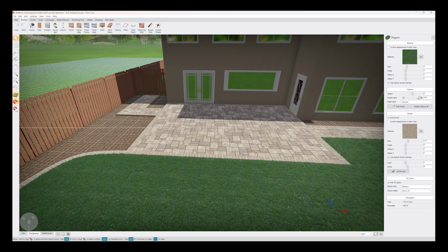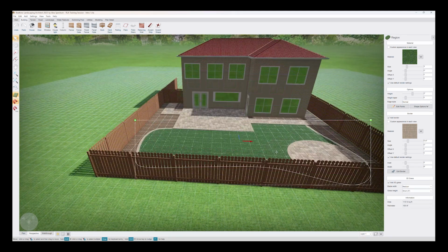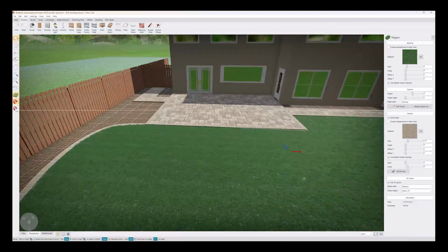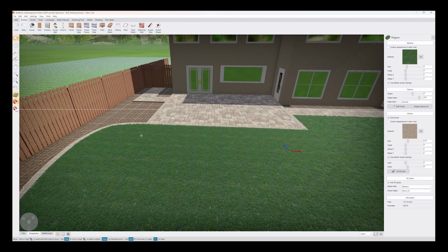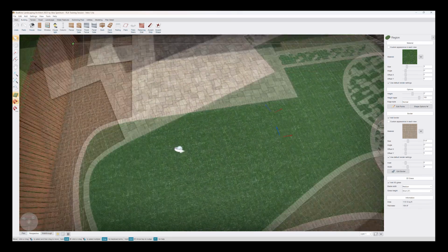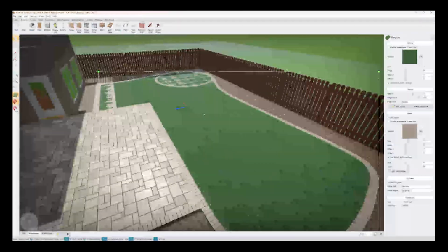The reason we did the height taper first is because if it's at 0, it does a weird bulge where just the middle of the turf area raises. We want it all to raise, so 100% makes the whole area raise 2 inches. That allowed us to raise the border and the turf across the whole area.